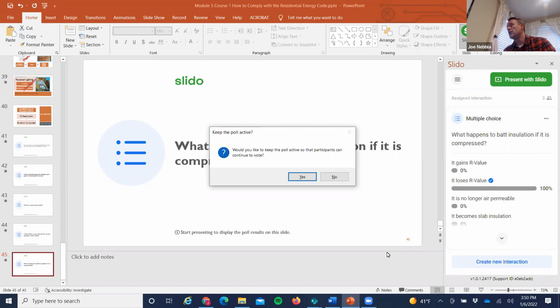And the code doesn't reference ResNet grade 1, for example. Right. That's a standard we talk about a lot, but when you look at what's described, it's really ResNet grade 1. Absolutely. I mean, grade 2 and 3 doesn't actually comply with the letter of the code. Right. So even though it doesn't reference that installation standard, really you would need to be at a grade 1 in order to actually comply with the energy code.